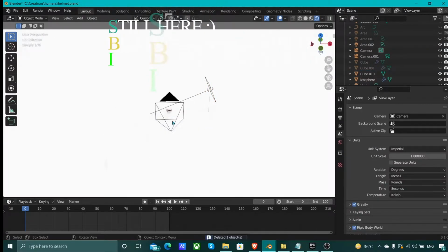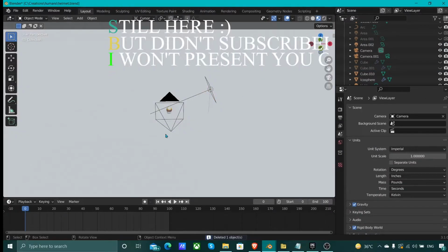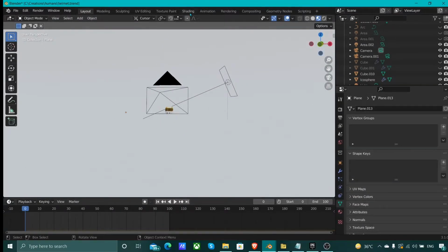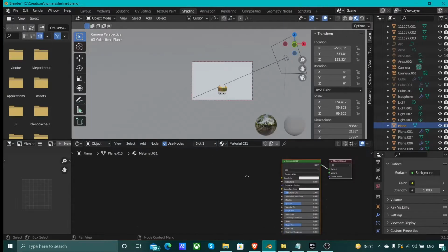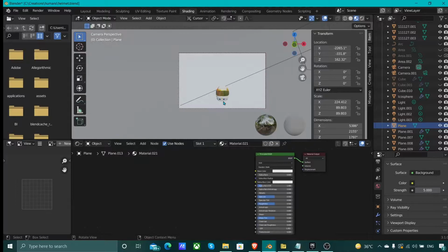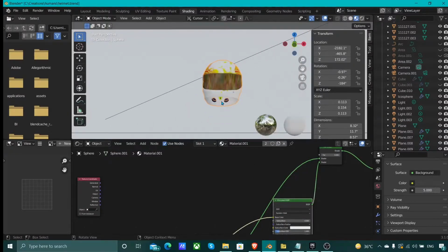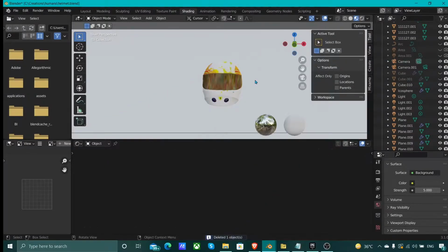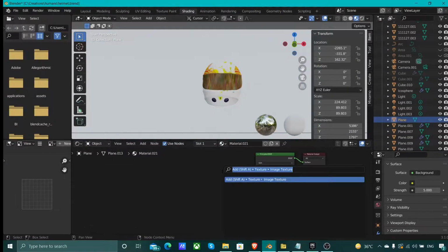Now, one more trick that I want to explain to all of you guys. You can use the ambient occlusion node in the node shader. This is the default shader that we get. In case you want a quick, decent shadow without much problems, what you can do is, let me delete the portal light first. Okay, so you can select the surface, press F3 and then search ambient occlusion.